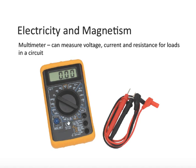And finally, if the dial is aimed somewhere in this area, notice the symbol here, it looks like an ohm, and it is indeed an ohm. This particular area of the multimeter can measure resistance. So this area measures voltage because there's a V there. This area measures current with the A, and this area can measure resistance with the ohm.